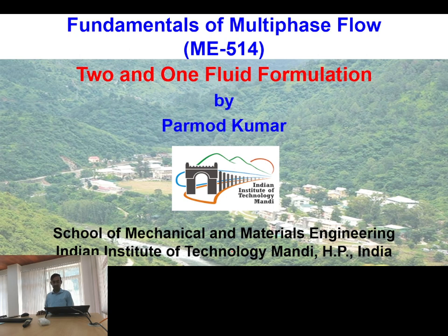I told you that we can resolve a multi-phase flow system in two ways. One is using the two fluid approach, where we are solving separate continuity, momentum and energy equations for each phase, and then at the interface we are providing the kinematic and dynamic boundary conditions. And the second approach is we will be using only a single set of equations, and then for the cells which are occupying the interface, we will use some sort of formulations to specify the properties of the mixture for the cells which are carrying the interface. Okay, and then some additional forces which are acting at the interface. So let me continue the discussion.